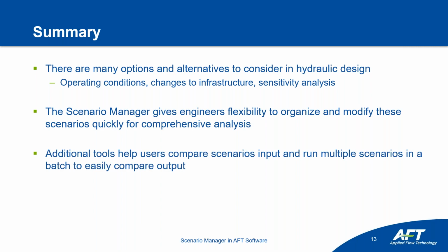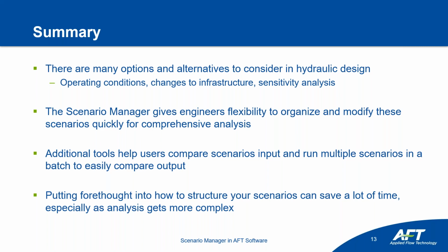We have a range of different tools that can help you compare scenario input, so the scenario comparison tool, or if we wanted to run all of our different scenarios at the same time, we can use a batch run. So the scenario comparison tool, again, from the tools menu, and then batch run from the file menu. And then finally, putting some forethought into how we structure our scenarios can save a lot of time, especially as our analysis gets more and more complex.